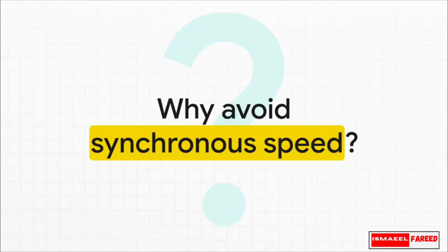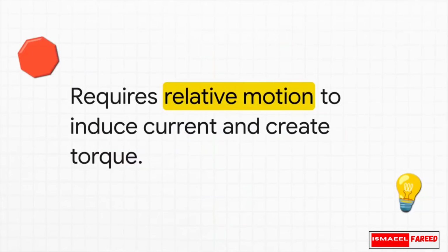Being able to just snap off this kind of proportional math in your head is a huge advantage in any interview. Finally, I want to leave you with this really fascinating quirk of electrical physics. We know the motor's stator creates a magnetic field spinning at a specific synchronous speed. But why is it physically impossible for the induction motor's rotor to ever fully catch up to that magnetic field? Well, think about it. If the rotor magically caught up and matched that speed, there would be zero relative motion between the spinning magnetic field and the rotor conductors. And without that speed difference, which engineers call slip, there's absolutely no electromagnetic induction. No induction means no current, and no current means exactly zero torque. The motor would literally just stop driving itself.